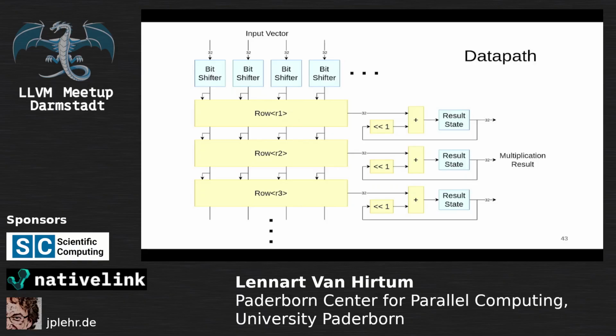Now, why would we do that? Within these rows, in a normal matrix multiply, we would have to have n by m bit multipliers. Now, DSP slices tend to get pretty expensive. But what if instead we were not multiplying n with m, but n with 1 bit?